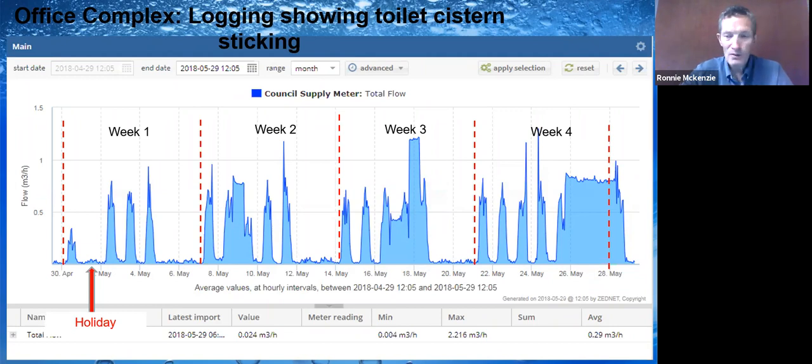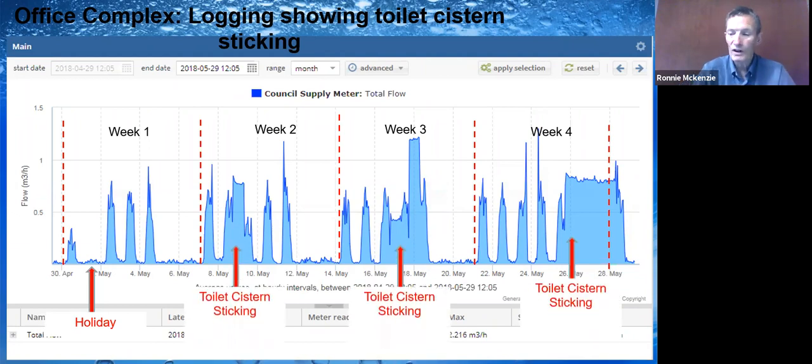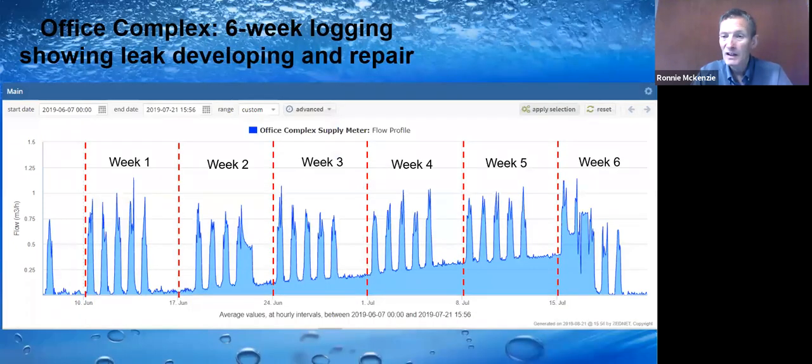And we find that they don't seem to work that well with the water quality that we have. The valve keeps sticking because we've got bits of grit and silt sometimes in the water. So we've had trouble with the dual flush toilets, not because they weren't good quality or properly made. It's just a combination of the poor quality in the water and the fact that we're not filtering the water perhaps before putting them into the toilets. So that was a problem. Our water consumption went up instead of down when we put in our dual flush toilets.